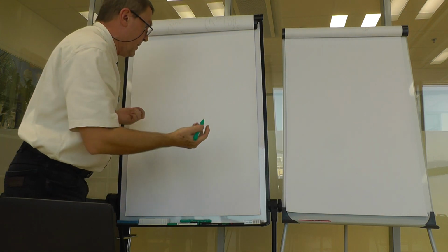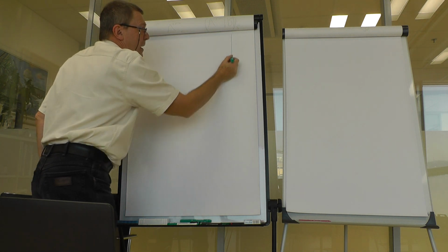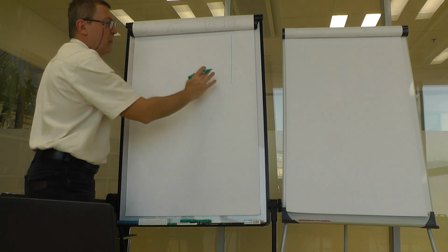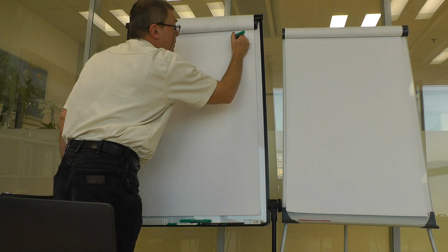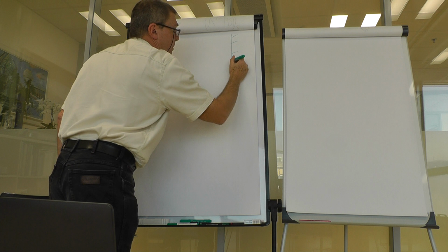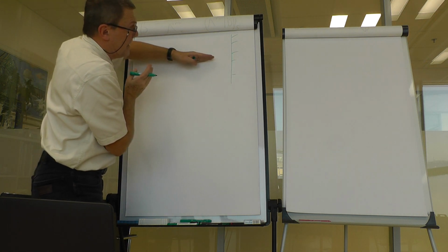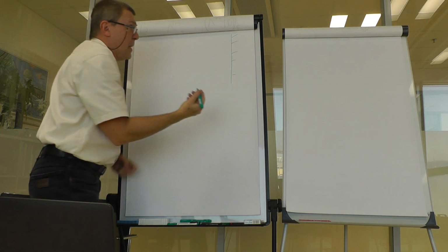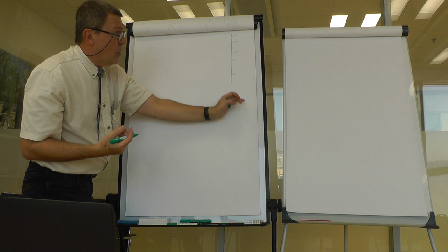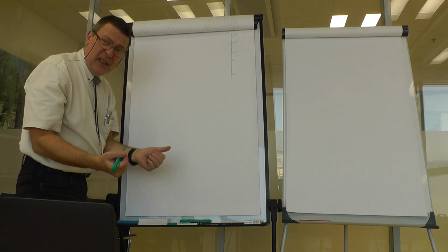We have an interface between two different media. Let this be a perfect conductor. And we have an electromagnetic wave perpendicularly reaching this boundary. You remember, this is a perfect short, so the reflection coefficient would be exactly -1.